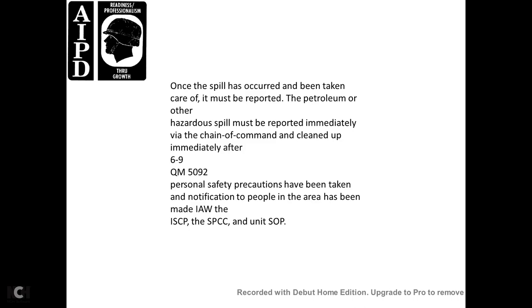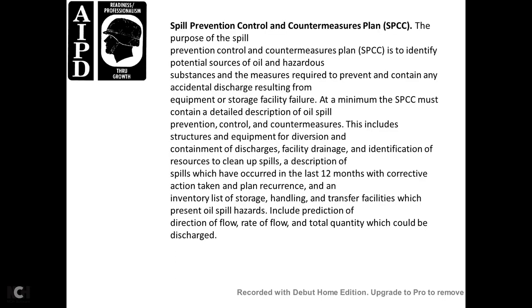SPCC. Once a spill has occurred, care must be taken, and petroleum spills must be reported. Other hazardous spills must be reported immediately through the chain of command and cleaned up immediately after. Personal safety precautions have been taken, and notification of the people in the area is made in accordance with the ISCP, SPCC, and the unit standard operating procedure.